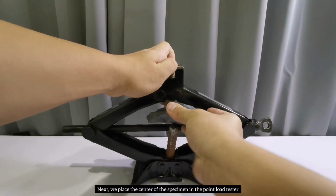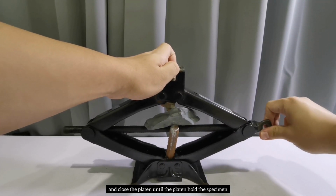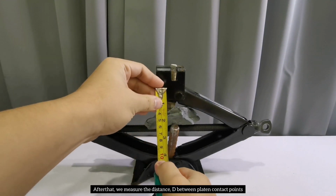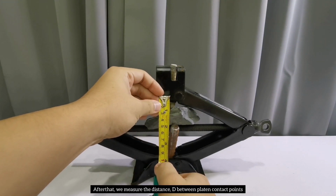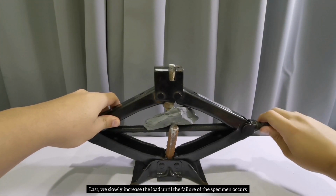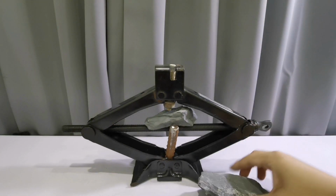Next, we place the center of the specimen in the point load tester and close the platen until the platen holds the specimen. After that, we measure the distance D between the platen contact points. Last, we slowly increase the load until the failure of the specimen occurs. We record it as the failure load P and repeat the experiment with different rock specimens.